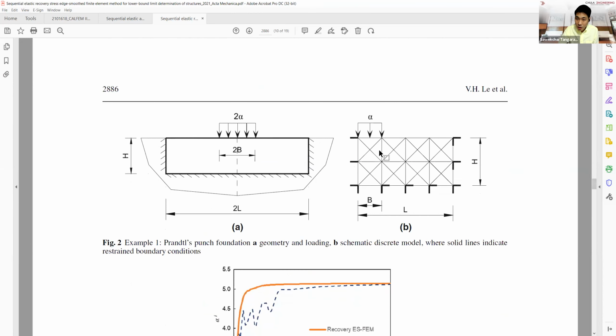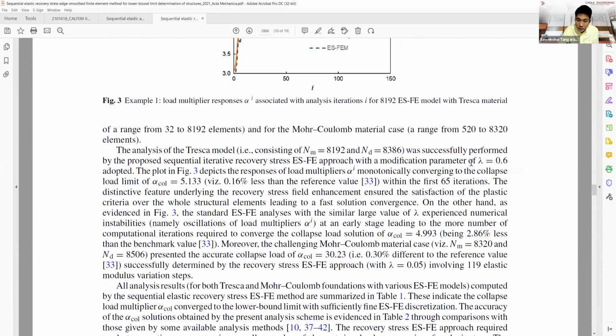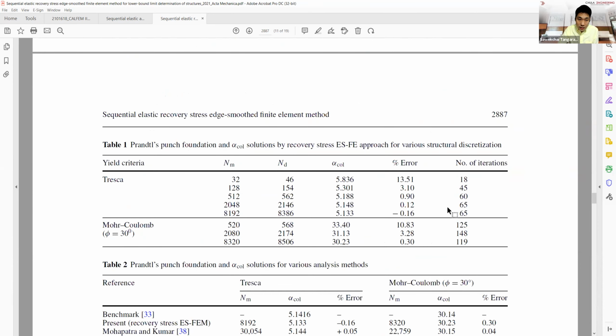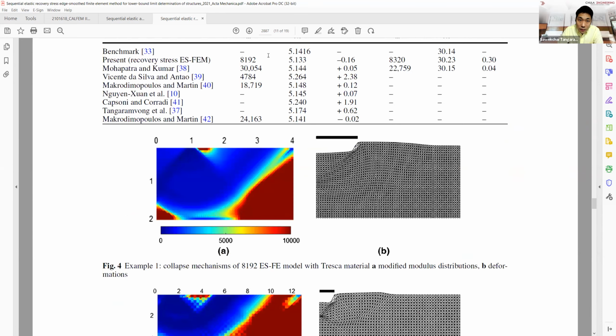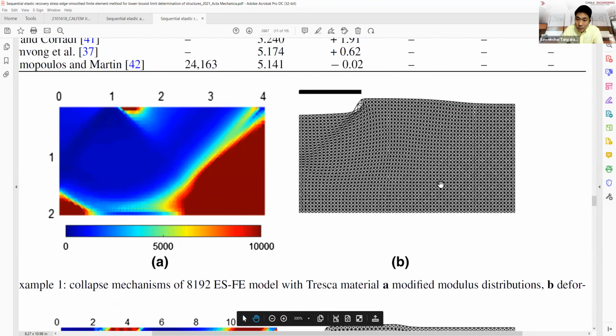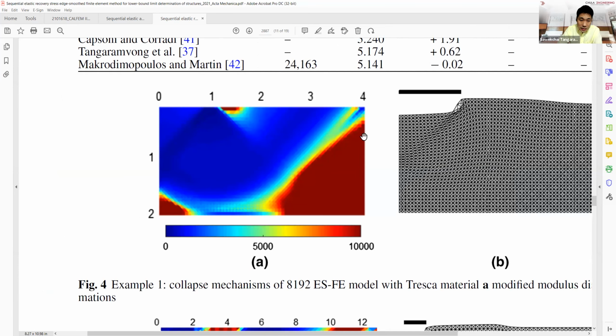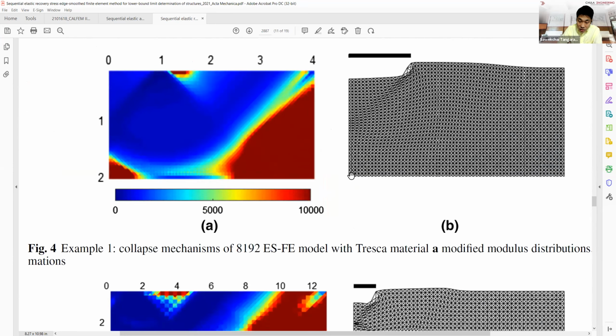You see, I start from the very coarse mesh. The mesh is not much because it's a coarse mesh, but I run the nonlinear analysis as well. When we check the accuracy, we talk in terms of the number of elements and we compare the accuracies. What I mentioned to you is if you do the uniform mesh, the way I subdivide the element is like you just draw the grid line, and the size of the grid line is so small. To get the accuracy, of course, we have the benchmark to compare, and we plot the convergence curve as well.